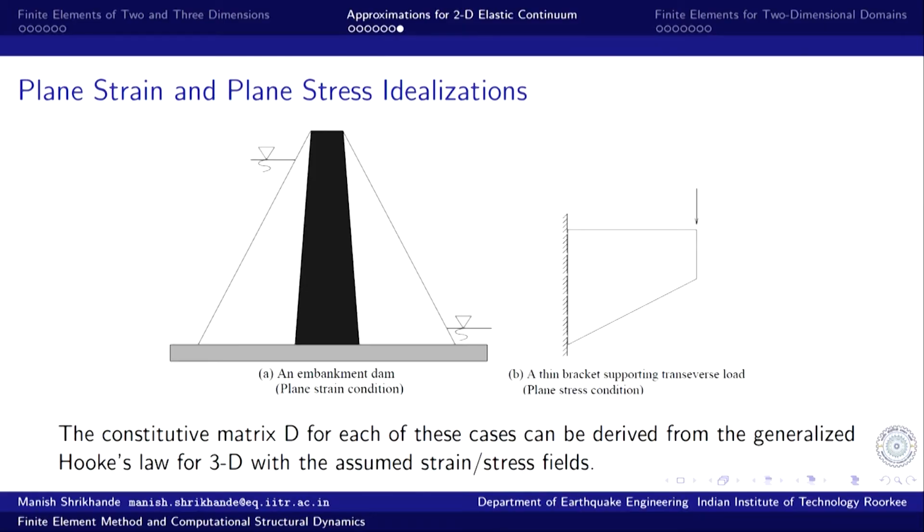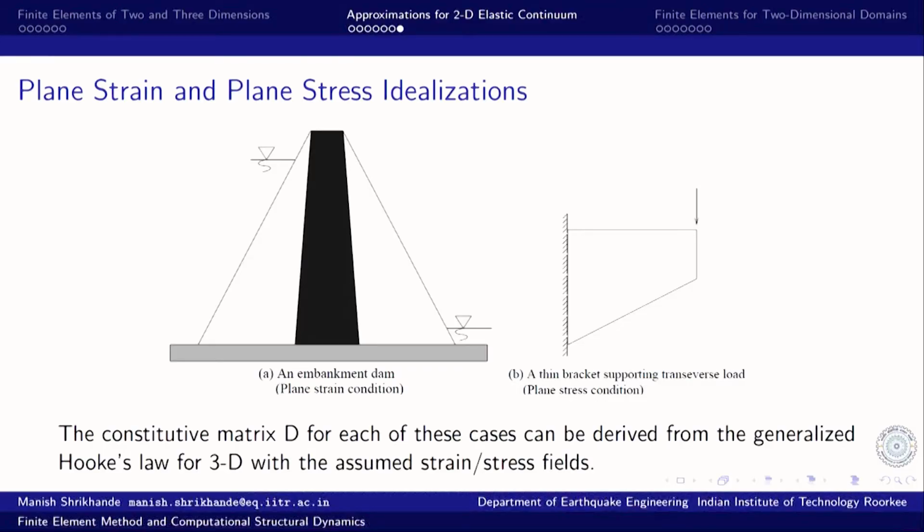The same finite elements can be used to model both plane strain and plane stress problems. There is another class of problems which are again 3-dimensional, but which are axisymmetric, symmetric about an axis. Those are what we call solids of revolution. Again, in that case if we model the problem using cylindrical coordinates, then we only need to worry about the cross section, because along the theta direction there is no change because of symmetry of the problem. So, there is no variation with respect to the theta direction.